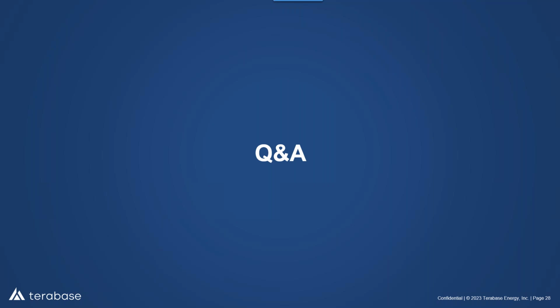we're careful not to say that this is the answer or that is the answer. We're providing you with the information so that an engineer can make that decision. We're providing you with all of the information, but not necessarily saying that the magic answer is 28 or 27. In our internal practice at TerraBase, we're using the P99.5 open circuit voltage at open circuit cell temperature. But we're a little bit careful not to take an extremely strong position on that. We provide you with all of the results in the report for both of the cell temperatures, if that makes sense.